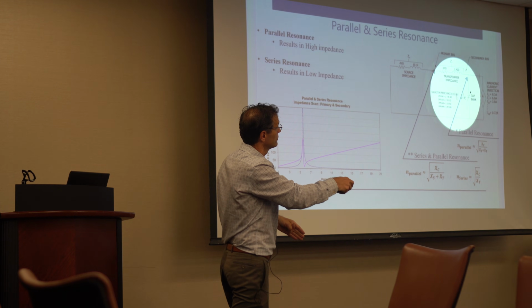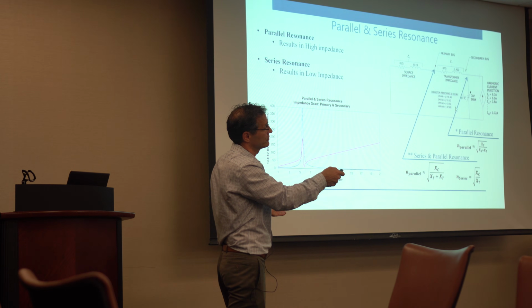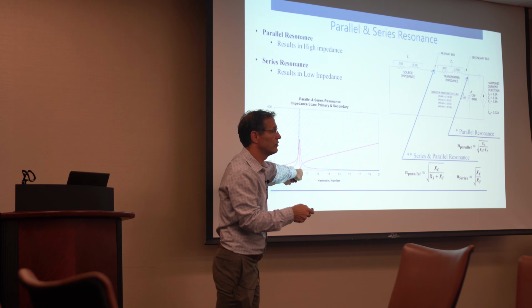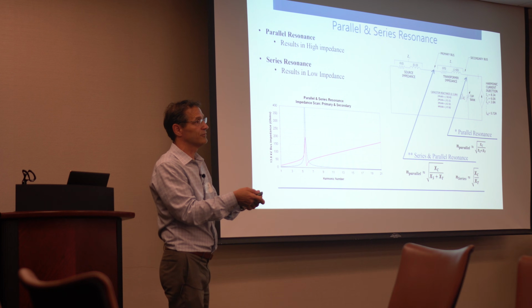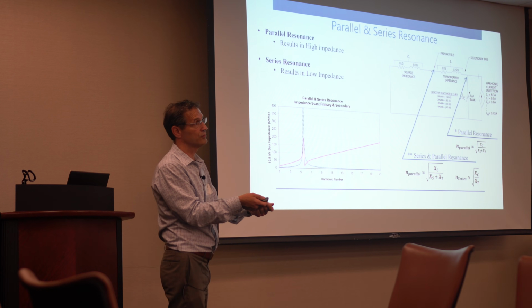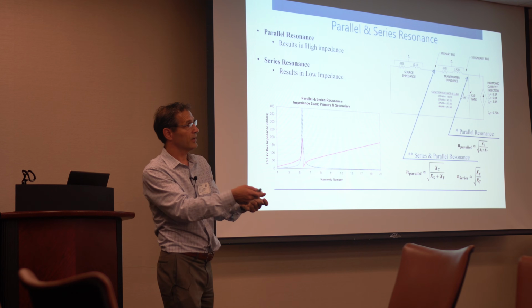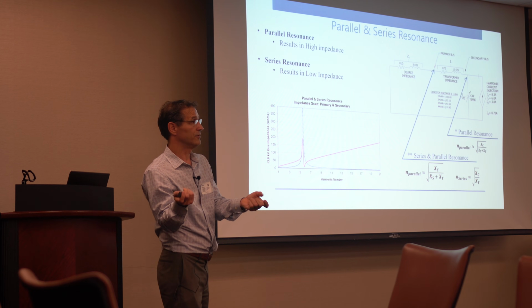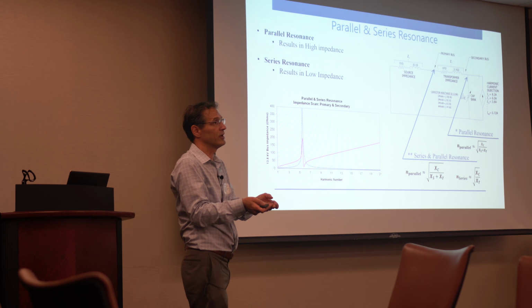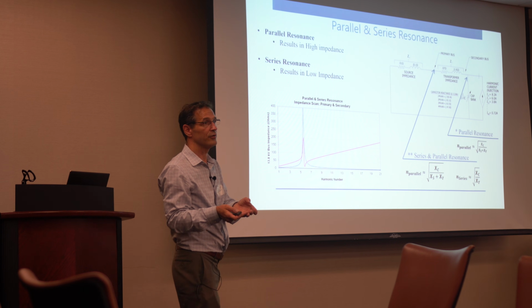You have this series resonance, technically a series resonance where it results in a low impedance. So it becomes a sink for harmonics from a medium voltage drive. If you have a large medium voltage drive, harmonic current might flow back towards the low voltage network and fail those capacitors, because the low voltage capacitor will not necessarily be able to handle that harmonic current.